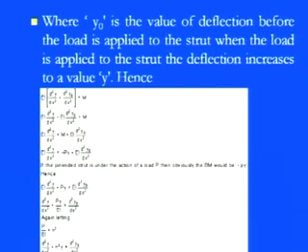So with that consideration, what we have as the resultant is EI into (d2y by dx square minus d2y0 by dx square), which gives you the real value of M. Or if you multiply those things, we have EI d2y by dx square minus EI d2y0 by dx square equals M. Or if you rearrange those things, we have EI d2y by dx square exactly equals M plus EI d2y0 by dx square.